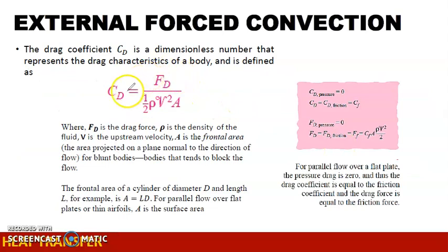This equation is your drag coefficient, CD. The drag coefficient is helpful in finding the value of the drag force. If you rearrange the equation, the drag force is just equal to CD times 1/2 rho V squared A.